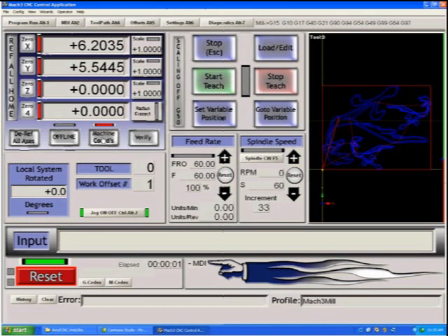Offline again, machine coordinates. And we have a verify button. The verify button is used if you want to check to see if you've lost any steps in your running of various programs. It will send the axes back to your home switch and then bring them back to where you were when you pressed verify and report to you any lost steps. Scaling off button will turn off any scalings that are in effect. If we had a scale of 0.5 on our X and we wanted to get rid of it, we could just press off. We have a stop button.